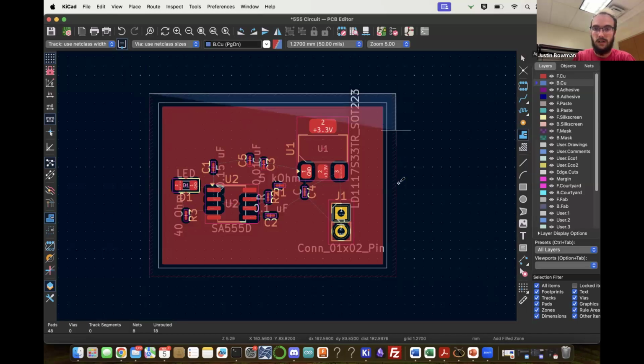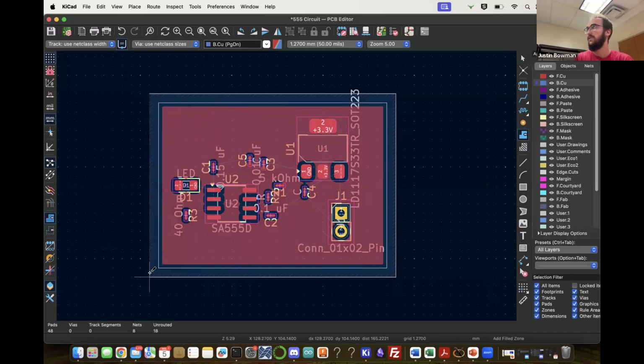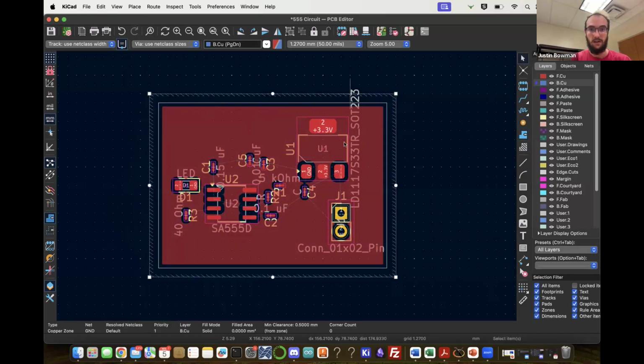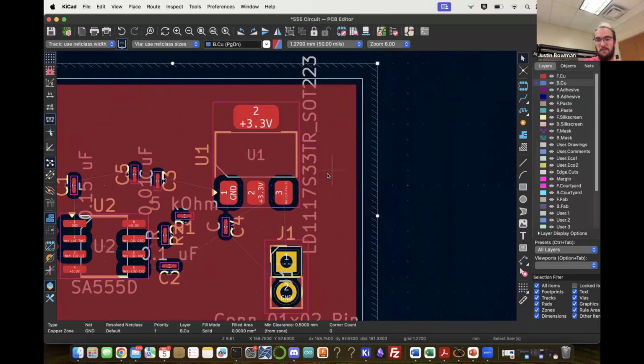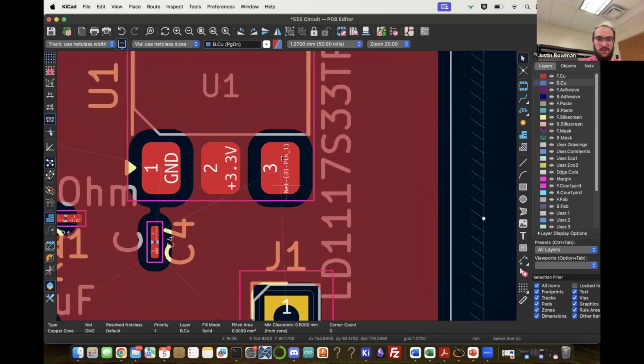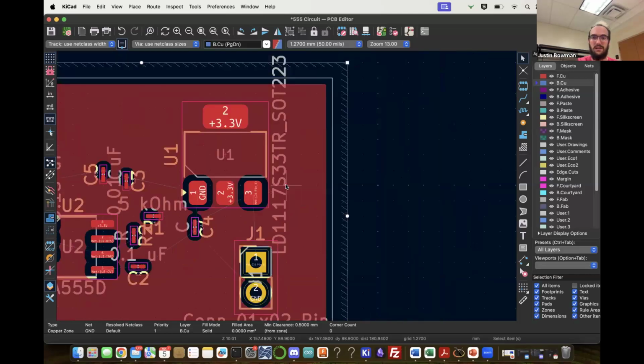Now we've put these components on the top of our board, so the solder pads on the footprint go to the front plane, which is why this separation between our copper plane and our pads is there, because we've told this copper plane is meant for 3.3 volts and only 3.3 volts. So these are left unconnected to our plane.